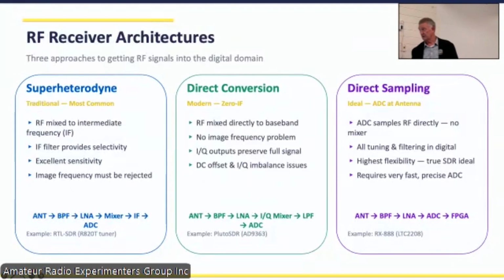Then you've got the direct conversion. That's only really been generally available for about the last 15 years, which is it's receiving the full bandwidth from the outside world and doing a direct conversion to digital. That happens today up to about 2 gigs. For your more expensive ones, the ones that you and I would buy, probably in the area of 500 to 600 megs is about the top end before it starts getting very ridiculous in price.